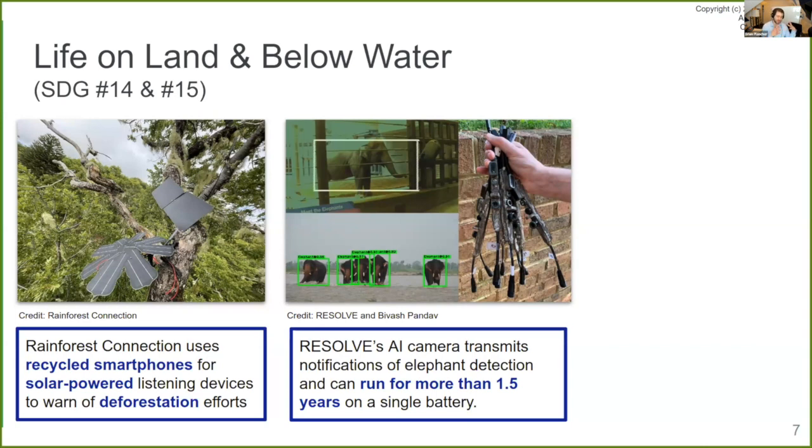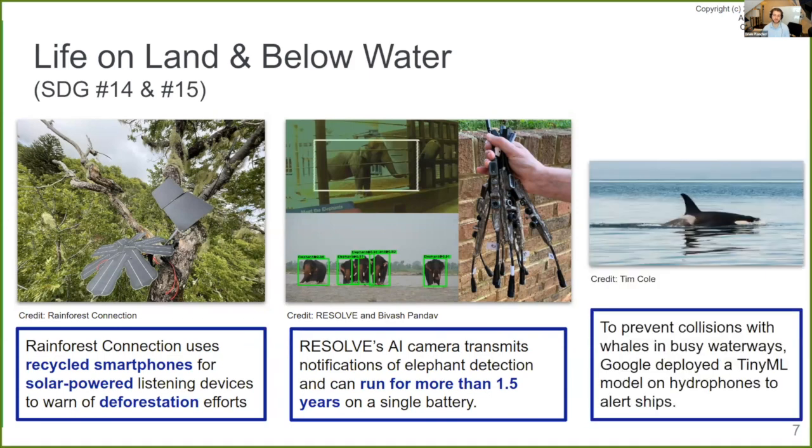In fact, a couple of folks have used TinyML on elephant collars to build smaller collars that you could put on, say, maybe even a lion, because a lot of those devices weren't having good battery life. But when you bring in TinyML, instead of trying to consistently stream real-time audio, you can instead listen on device, turn on the LoRa, and send a small ping when you need to.